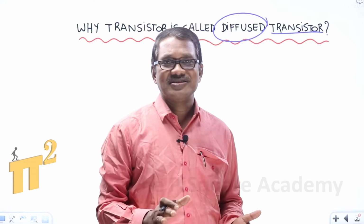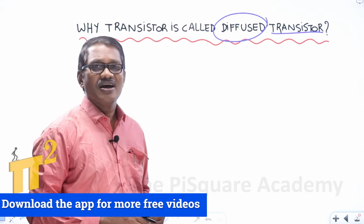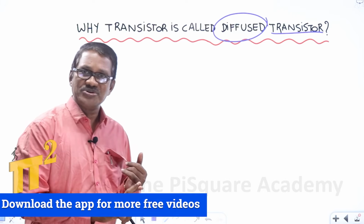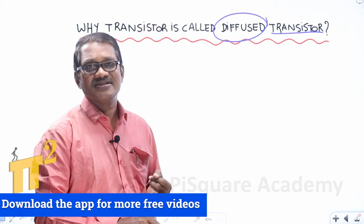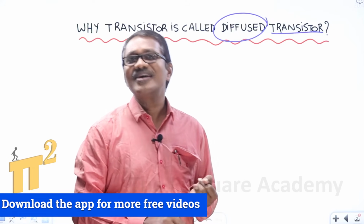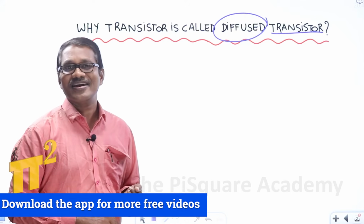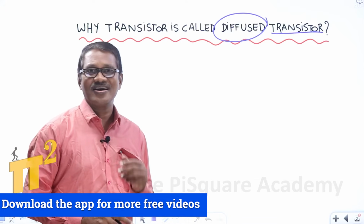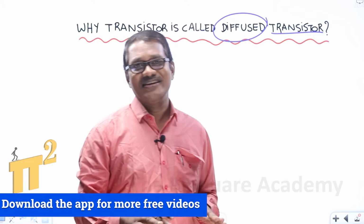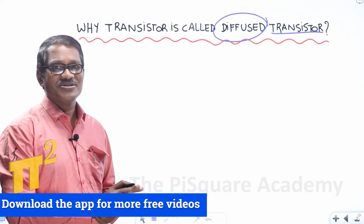due to majority charge carriers and is of diffusion type. In semiconductors, how many types of currents will be coming into the picture? Two types. One is diffusion current and the second one is drift current. Drift current exists in conductors also, but diffusion current does not exist in conductors. Diffusion current exists only in semiconductors. Two types of current components will be coming in: diffusion current due to concentration gradient, and drift current due to external field. Have you understood this, right?